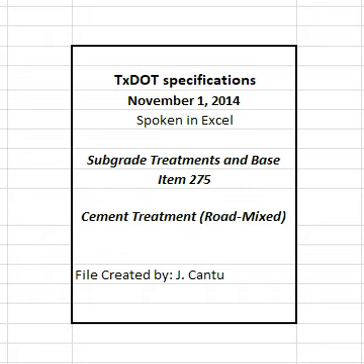2.2 Subgrade. The engineer will determine the sulfate content in accordance with TEX 145E and organic content in accordance with TEX 148E before cement treatment begins. Suspend operations when material to be treated has a sulfate content greater than 7,000 ppm or an organic content greater than 1% and proceed as directed.